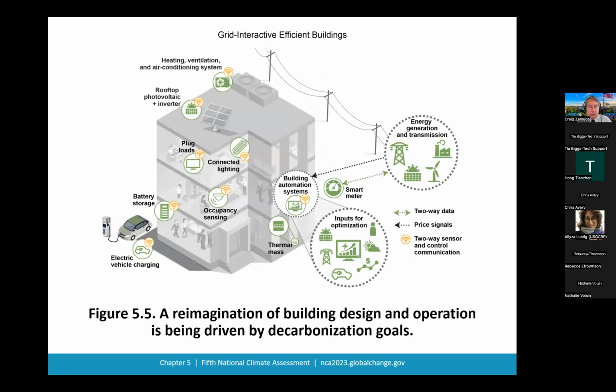Thanks, Craig. The buildings sector consumes about 40% of U.S. primary energy and contributes to 29% of the greenhouse gas emission. Climate change influences buildings in multiple ways. First, the warming effect increases cooling loads and decreases heating loads of buildings. Secondly, more buildings will need air conditioning during summer. Thirdly, the more frequent or severe extreme weather events, such as heat wave or cold snap, coincident with grid power interruptions, increase health risk of occupants due to exposure to indoor heat or low temperature and